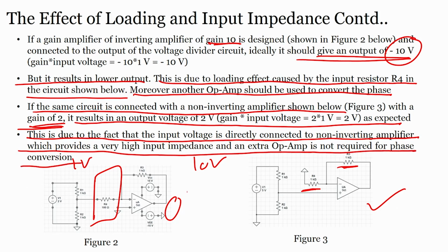So, if we talk about the inverting amplifier and the non-inverting amplifier, here what we see is that we can use non-inverting amplifier to remove the loading effect. There is no phase shift, and that is why for this particular application that we have taken as an example, this can be a good circuit, alright. So, this much is easy.